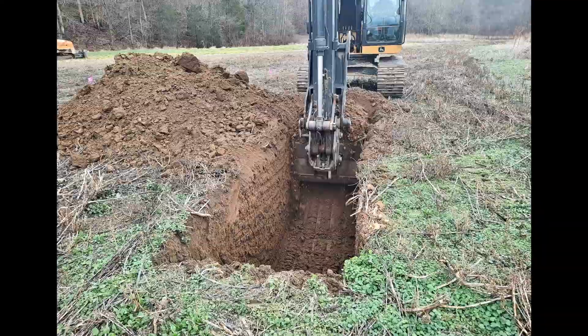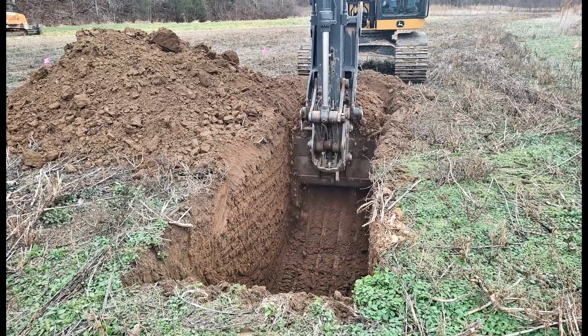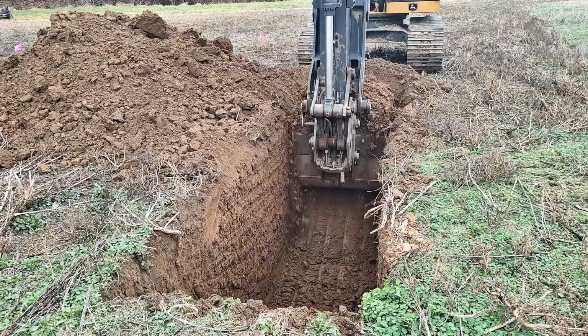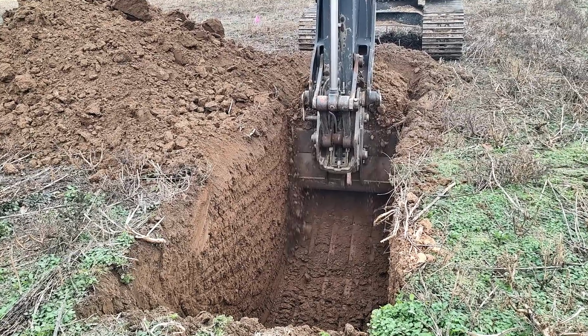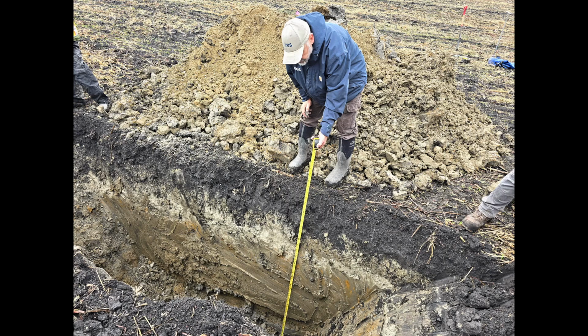It is necessary to dig one or more deep test holes within the area where you'd like to build a wetland to determine whether or not it's possible to build a groundwater dam for your project. Dig the test holes as deep as the machine or the soil auger you're using will allow. Measure the texture of soil by layer.